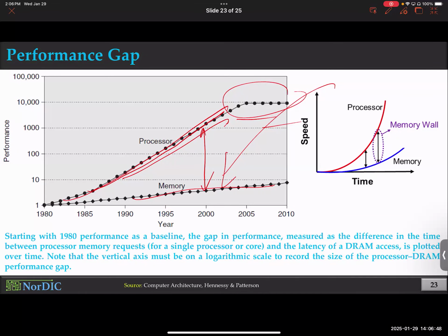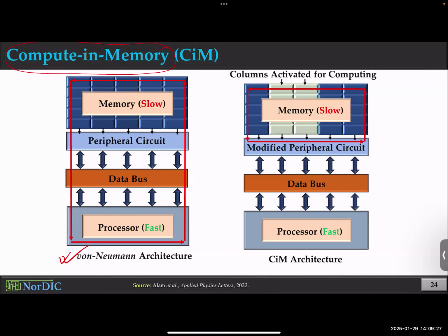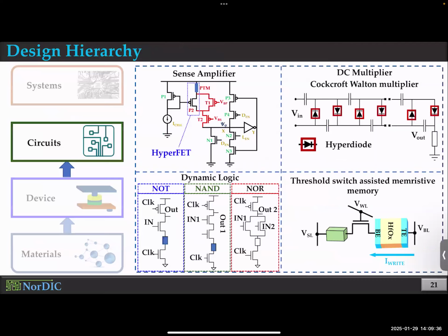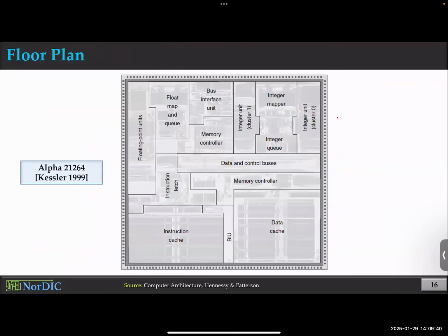Okay, you'll have a decoder, you'll have an encoder, you'll have a sense amplifier here, you'll organize the rows, you'll organize the columns. This planning, this high-level planning, is called architecture. Obviously, it's more complex than that. It's quite literally, let me just go back to this diagram. This is more like it, an even higher-level architecture. Where will the controllers be? Where will the processing units be? All of these high-level details fall under the architecture, okay?